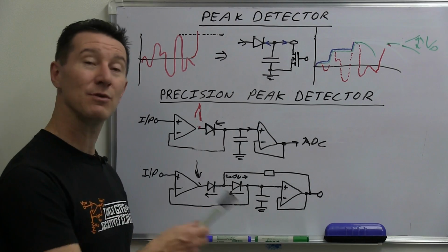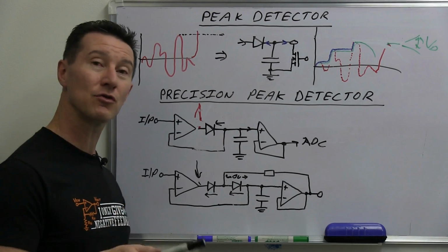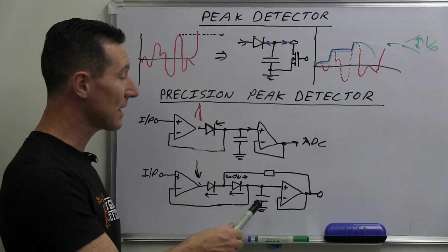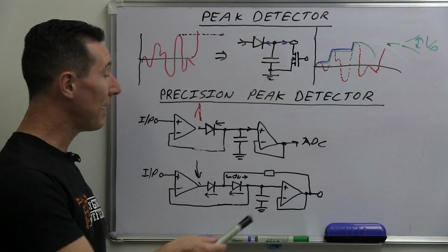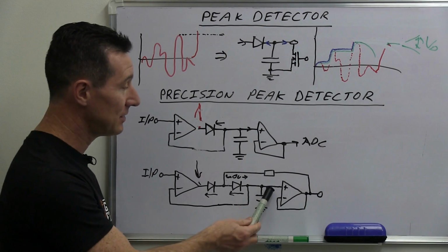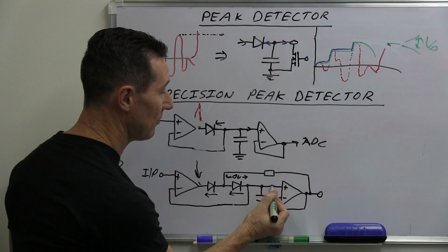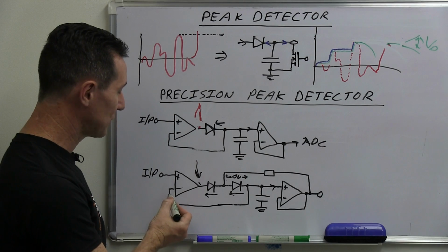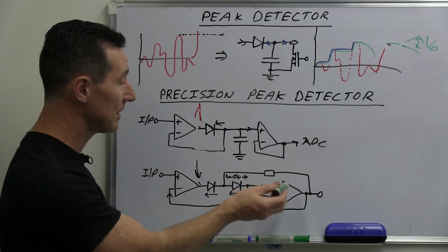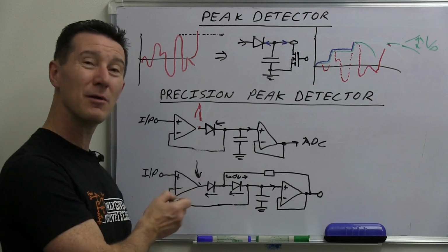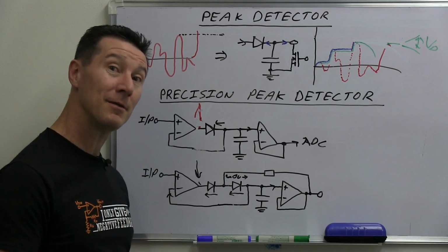And of course, as we've seen in the tutorial previously on input bias currents, you can get very, very low ones, in the order of femtoamp op amps. And you're going to need 2 because not only do you have the bias current flowing in there like that, but you've also got the bias current flowing in there because that's connected in parallel across the cap. So you're going to want to choose 2 pretty schmick op amps in there. So there you have it.